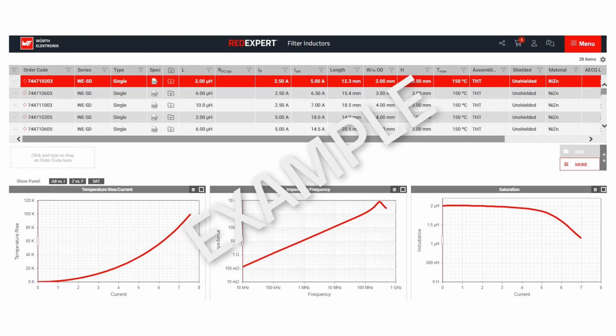All this data which you will find here is the same as in the data sheet, but because it is measured value, you even have the possibility to see what happens when you put this device at minus degrees, like minus 40 degrees. How much is its inductance dropping? How much does its saturation move, especially in a very hot area? You may have some inductance which is operating above 100 degrees Celsius, and that means the inductor will saturate a little bit earlier. But how much earlier? No manufacturer tells you until today.